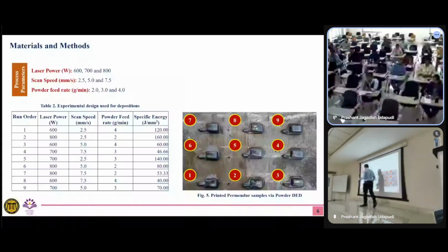But the problem there was we could not establish a pattern. Usually if you increase the laser energy, the slope decreases or increases, right? That's a right pattern. If we come to know that, we now know exactly how to tune the properties of materials, right? By just changing the energy of the laser or changing the feed rate or scan speed.